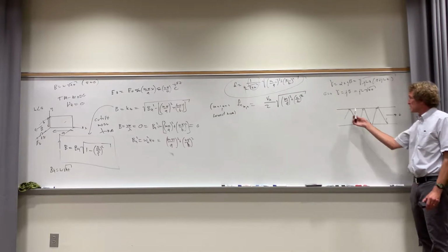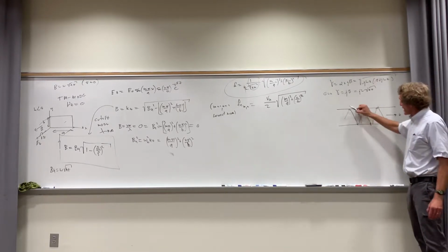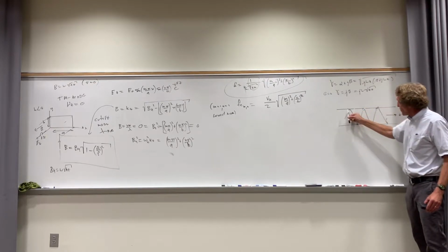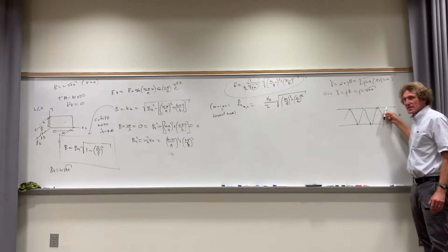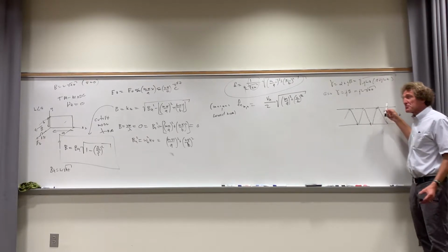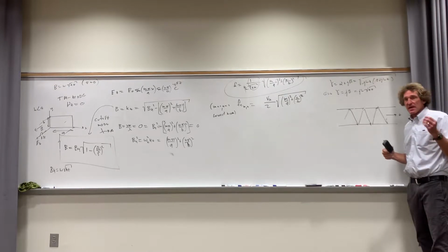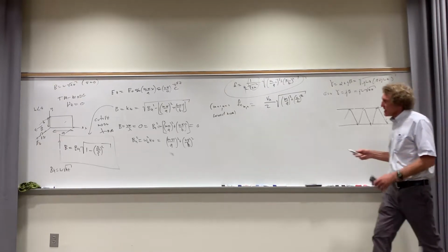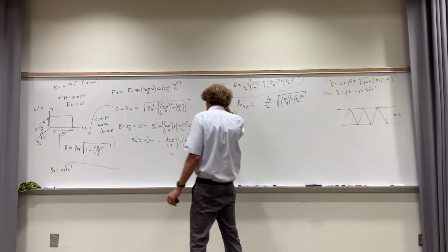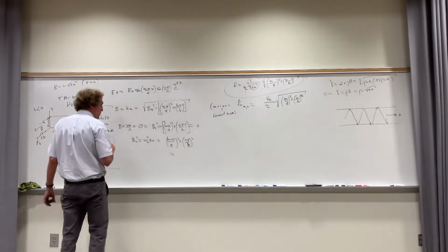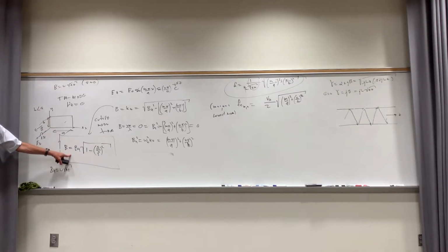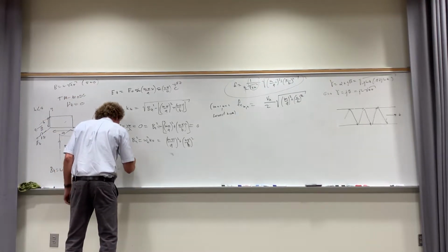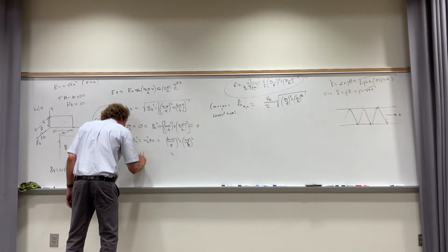Now phase velocity, remember I told you how it's really kind of an abstract thing that has to do with the point where the wavefront intersects this surface right here. Do y'all remember that? Phase velocity is an interesting term, but it is not to be associated directly with energy. Let me show you how to get this. So this is beta right here in a waveguide. The phase velocity, V phase, is always going to be omega divided by beta.